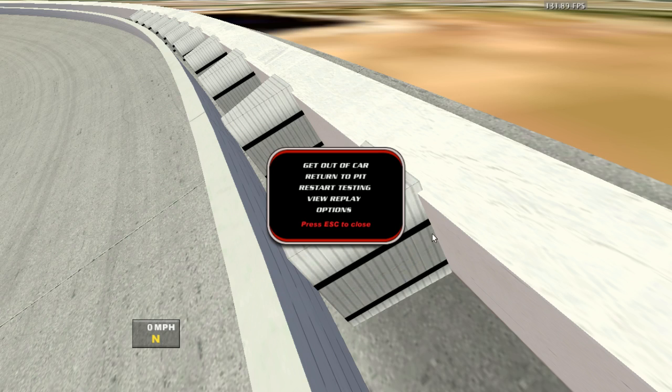If you start freaking out because it doesn't look right in Sandbox, check it in game before you make any changes. Make your adjustments based on what you see in game, not what you see in Sandbox. What you see in 3ds Max and what you see in game should be a lot closer. So make your adjustments based on that information. Obviously the height of the wall has to go up a little bit. That will also bring this edge of the wall up here a little bit. That will take away some of the over rotation into the wall that you have.